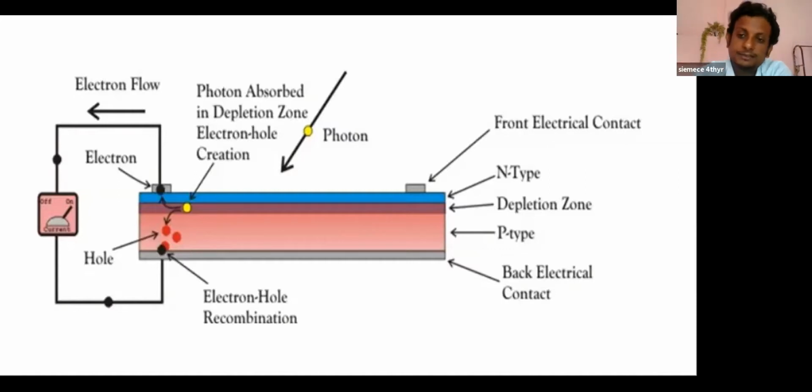Now when light reaches the PN junction, as you can see in the diagram, the light photons can easily enter the junction through the very thin P-type layer. Though the configurations may be altered, the light energy which enters through that layer and hits the junction can generate a pair of electrons and holes.